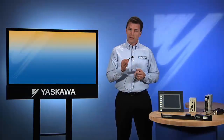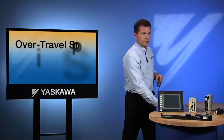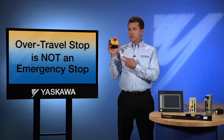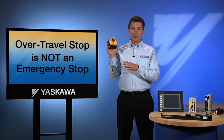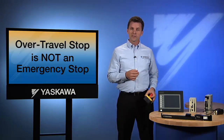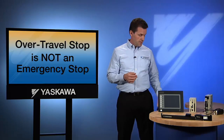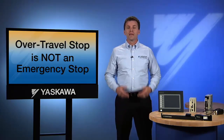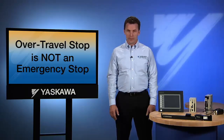Damage, or even injury might result. It pays to remember that an over-travel stop is not an emergency stop. An emergency stop would prevent all motion in all directions. An over-travel stop is simply a quick way to stop motion in one direction. In an over-travel condition, the controller can be programmed to recover and the servo can still be moved in the opposite direction.